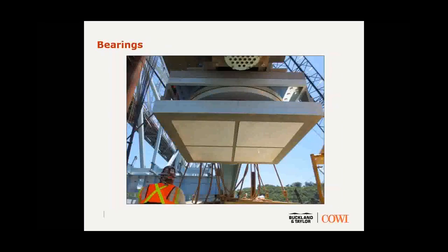Bearings had to, well, they're large truss bearings, of course, this being a heavy truss. All the loads come down to single points. This bearing is between 5 and 6 feet square. There was some accommodation made within the bearing design to accommodate the sliding. That's what you're seeing in the bottom of this bearing. In this photograph, you can see 4 inlaid panels of dimpled Teflon. That actually becomes the sliding surface that the entire bridge was slid over on the temporary piers and onto the permanent piers. I'll have a bit more on that later.